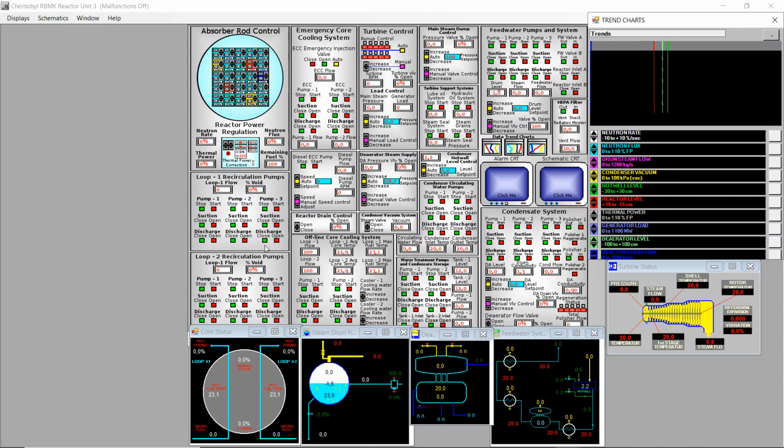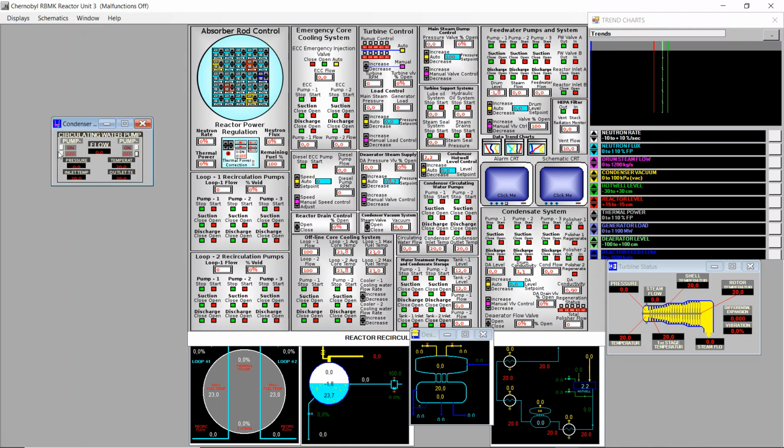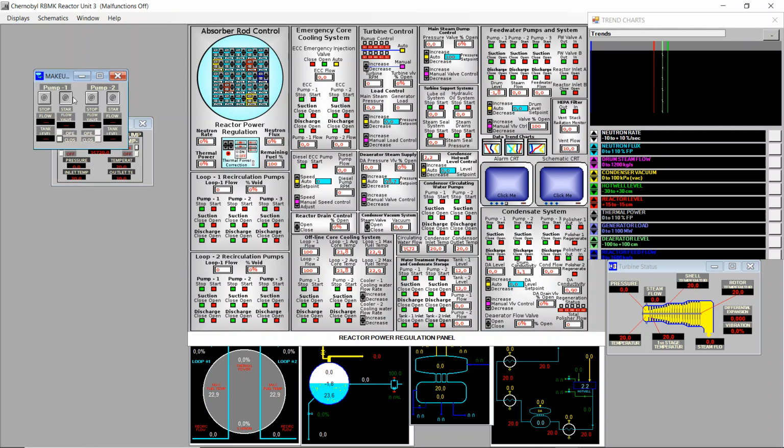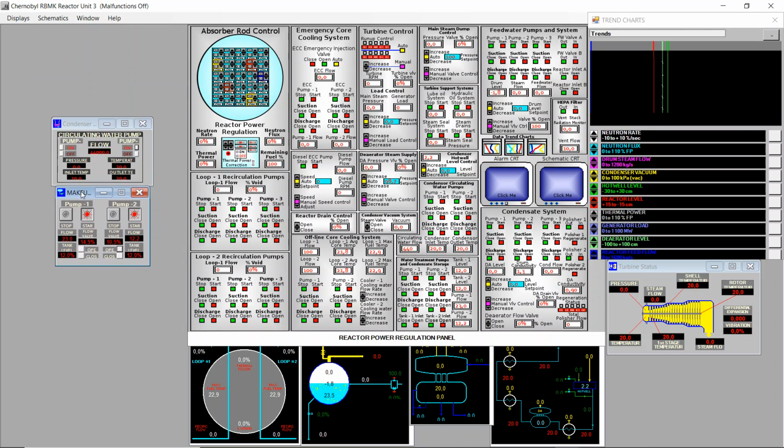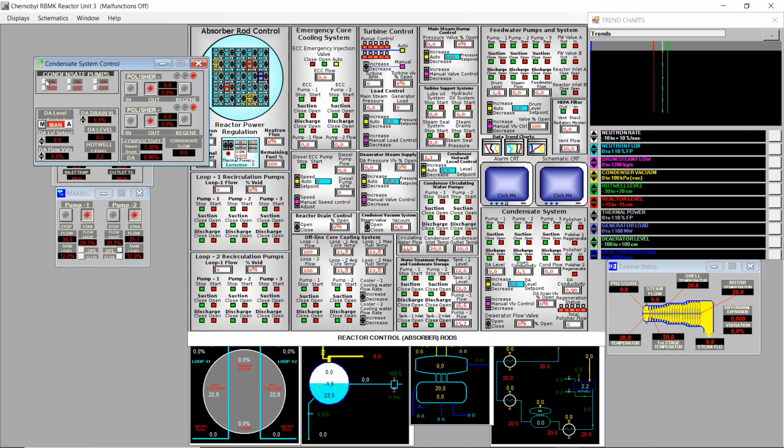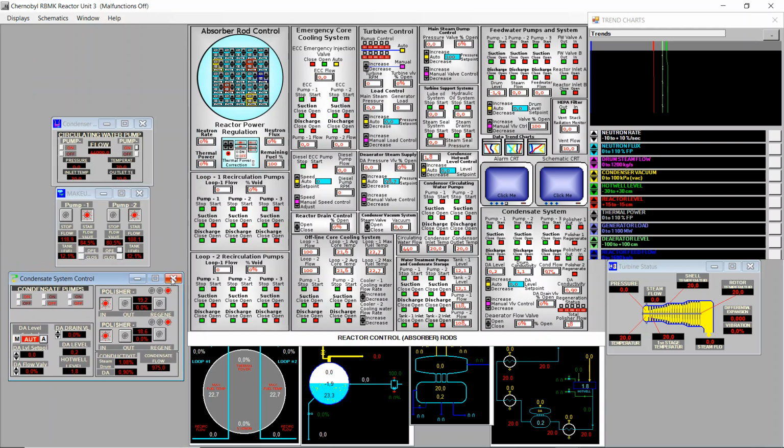Okay, so let's start. First of all, because the reactor level and hot well level are correct and stable, we can already start turning on the condenser circulating pumps, the two water treatment pumps, and also the associated valves. Condensate system, we turn on only one of the 3 pumps for the moment and set it into auto. The deaerator level set point is at 0. And we turn on the 2 polishers. Okay, these 3 things are fine.